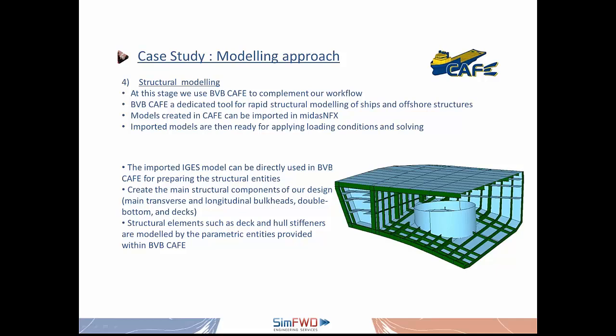We have been creating models in CAFE because it is intended for ship structural modeling, and it has functions that allow you to very rapidly define the outer hull and also the internal structure, like dedicated beams, parametric stiffened panels, openings, brackets, and all other structural elements related to shipbuilding.